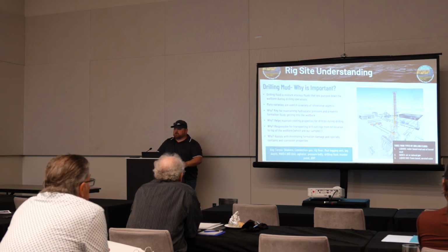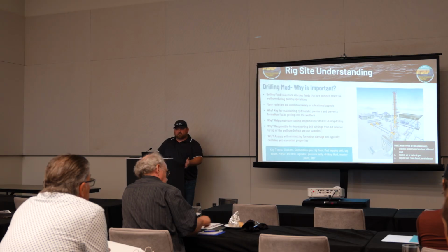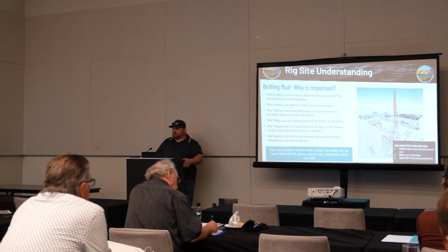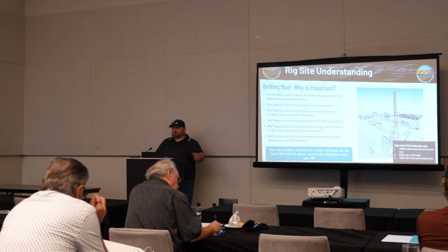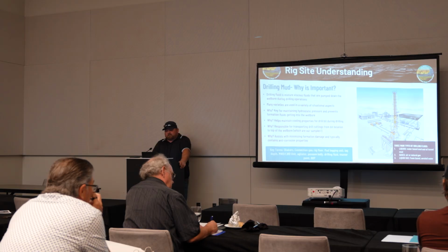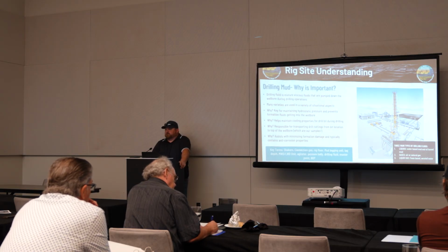A big thing that mudloggers get confused with is mud engineers. And yes, for people that don't know what a mud engineer is compared to a mudlogger, we're both mud. We look at rocks, they don't. They don't care about what that rock does. So, in that sense, for us to know what the drilling fluid is doing, it affects our gas readings. If they're running high mud weights, that's obviously going to suppress the gas back into the formation. We're not going to read it because it's not being introduced into the wellbore.